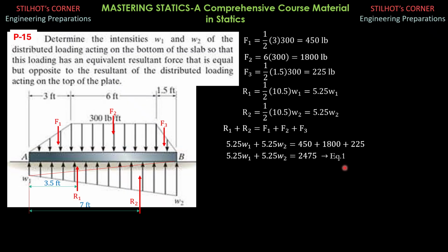Then for the second static equation, that is the moment equation, as I said, I select A as the reference moment center. After this problem, if you have time, I want you to select point B, and if you want to extend it further, just to master the principles, you can invent another point here. So let's say point C, 4 feet to the right of point A. You can select that as the moment center if you want.